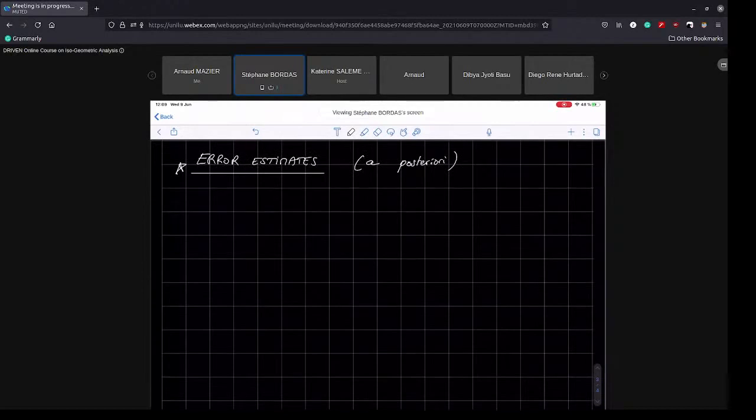Again, what we're doing is computing the error between the exact solution, U, and the numerical solution, UH, in some norm. The goal is to see where this is going to be high. So the goal is to have a map of, let's say, E is high here, E is low here, and E is medium there. That is the very basic way of thinking about it: where is the error high in the domain, and where is the error low?